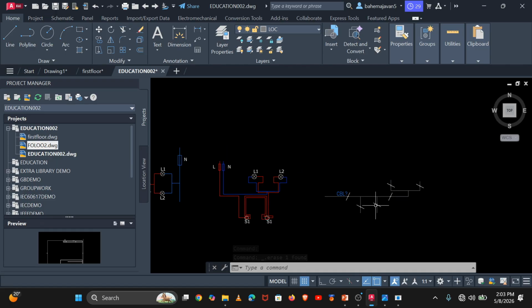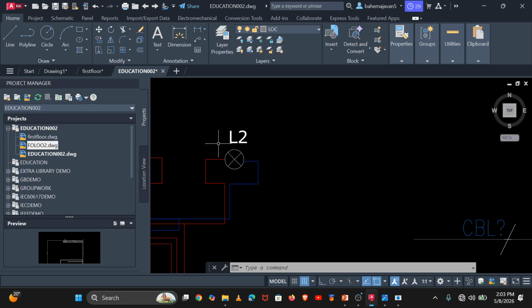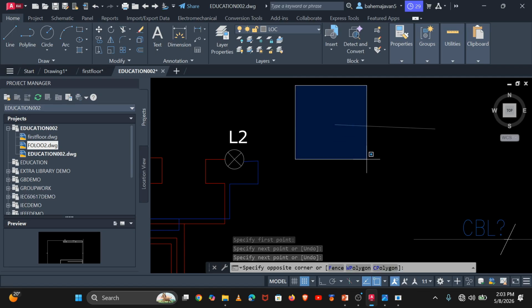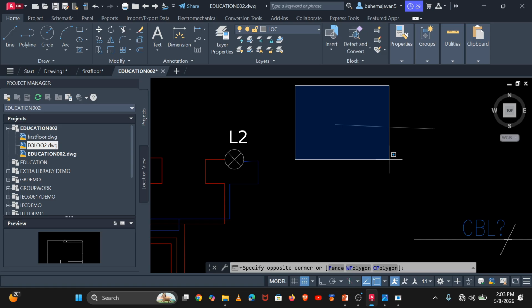Even the lamp, let us copy this lamp right here, and we will use lamp. There is a type of selection that I have taught there first. For example, if I draw the line and then hit enter, when I copy like this, by the middle of the line I cannot copy the whole line. The blue select box only selects everything that is contained inside that box. We must know it very well.